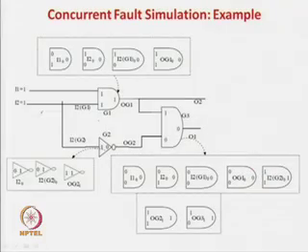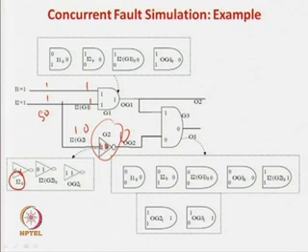So, now let us look at it, it is 1 1. So, 1 1 and in this case is a 1, it is a 0. Now, let us study for this inverter what will be the cases. So, for the inverter you can easily find out that normal case it is a 1 and it is a 0. So, if this net is stuck at 0 over here obviously, so this is I2 0. So, if I2 0 what happens? So, this one will be 0, this is stuck at 0 and this one is 1. So, this is reflected by a stuck at 0 fault here, that is the change for this gate.